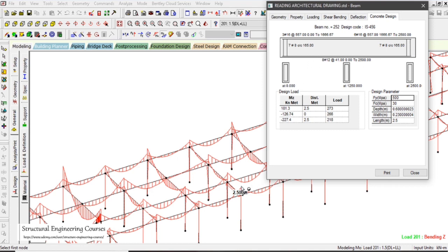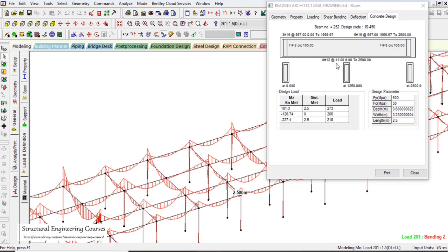It is saying that as per the tentative, or conventional, detailing as per IS 456, the area of steel required is 3 number 16 dia on the top here, and 6 number 16 dia on the top here, and at the bottom we can have 8 number 12 dia bars. Although in 230 mm width we cannot accommodate 8 number 12 dia bars. That is altogether a different approach, which is why we need to understand the detailing that we need to do in our structures.